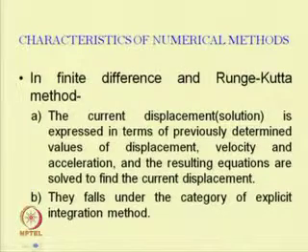So, in the finite difference and Runge-Kutta methods, the current displacement solution is expressed in terms of the previously determined values of displacement, velocity and acceleration, and the resulting equations are solved to find the current displacement. They fall under the category of explicit integration methods.